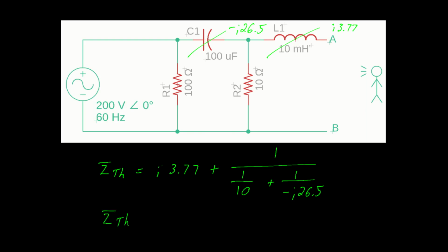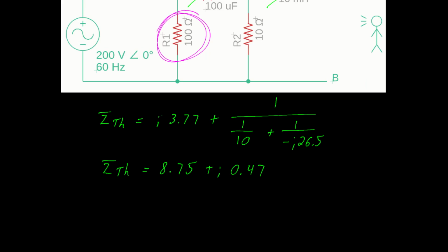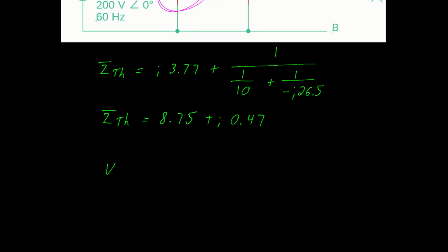Again, that 100 ohm resistor is not part of the equation because when we conceptually shorted the power supply, we took the resistor with it. You could think of that resistor as part of the power supply if it helps.